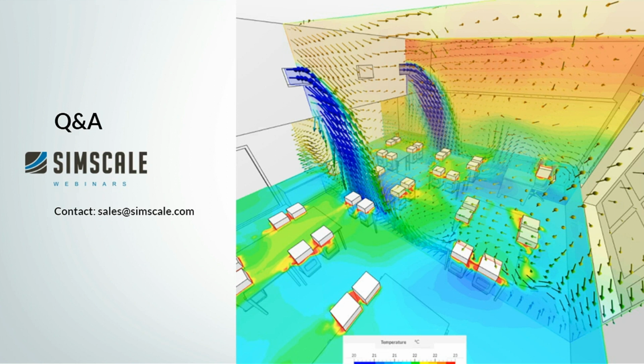Great. One other question was regarding the mesh controls. We have quickly touched on it already. In general, the meshing approach on SimScale is that we try to automate it as much as possible, and we do physics-based meshing. If you follow the steps as shown by Ajit, you first set up the physical problem, and then you start a simulation, which in the first step will compute the mesh. The mesh computation algorithm will take all the information available from the simulation setup and automatically adjust the mesh behavior in an optimal way in general.